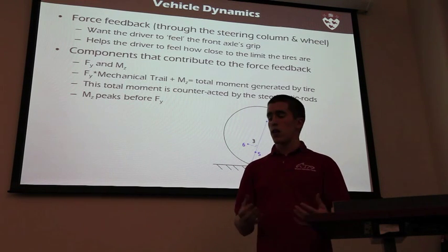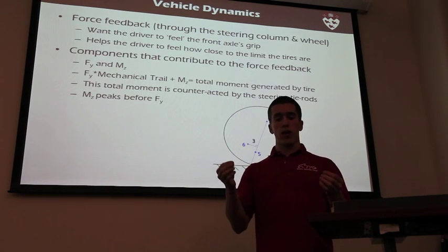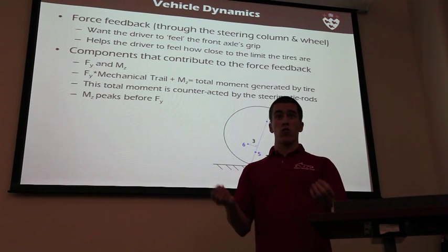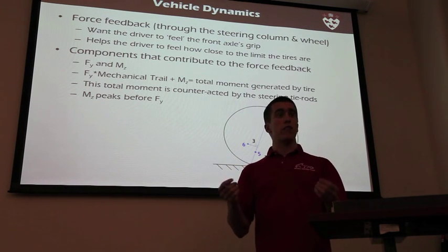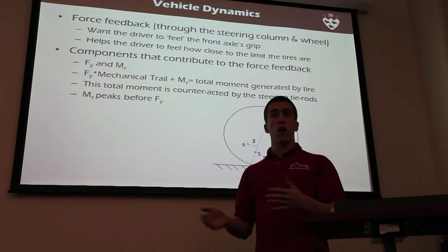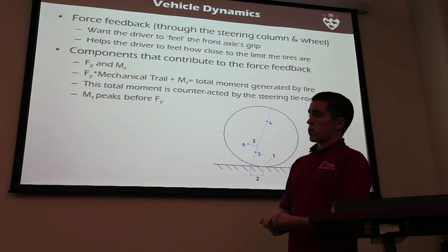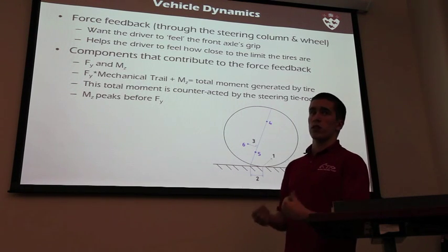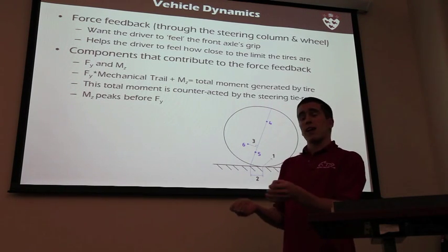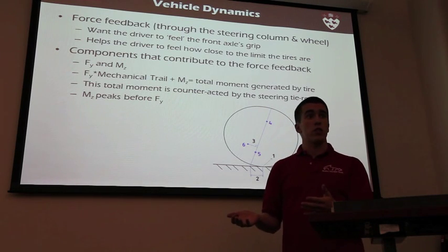If you're driving the car and the steering wheel has no feedback at all, you will not get a feeling of if the front tires are losing grip, are you going faster in the corner or not. So you want that feeling to be represented for the driver to feel how close he is to the maximum lateral acceleration the car can achieve.